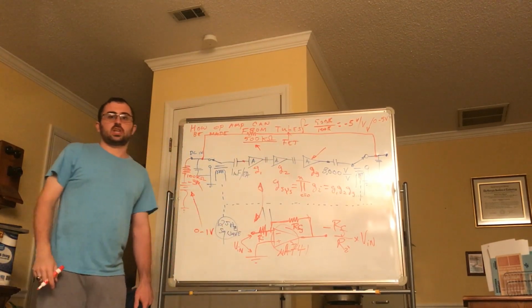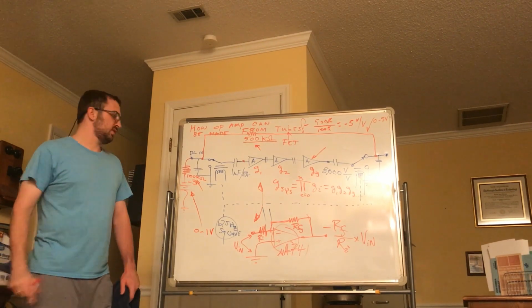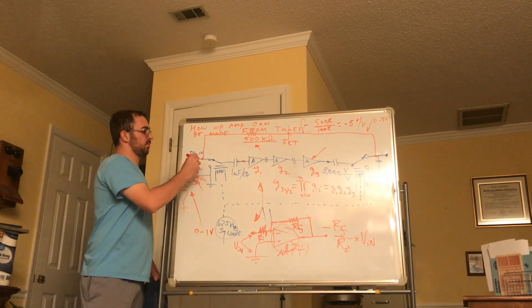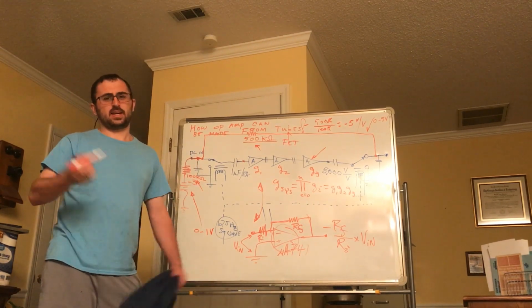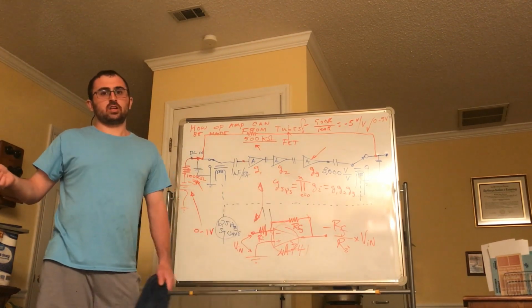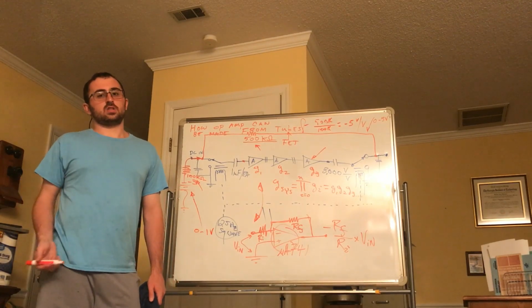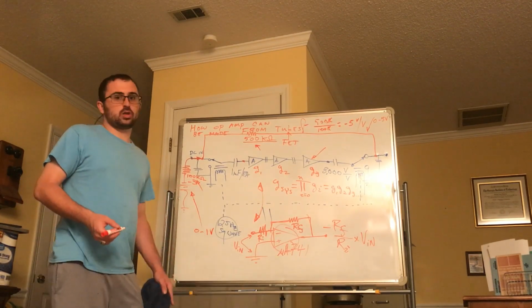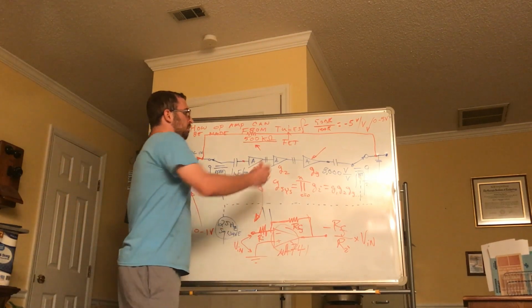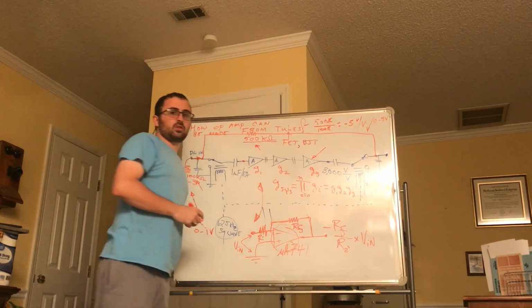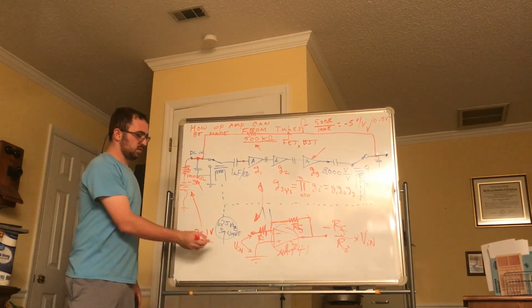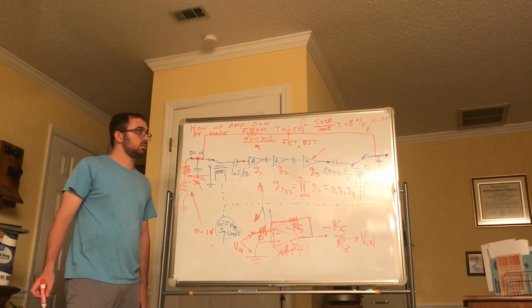For some reason, BJTs do not work well to build op amps, namely because they have a low input impedance, which is bad, and they have a very high output impedance. I mean, the collector of those things is really a high impedance, and you can use emitter followers, but they lose voltage, the VBE drop. Maybe you could use a BJT if you were clever. But the tubes work really well, and I will now show this instrument in operation.